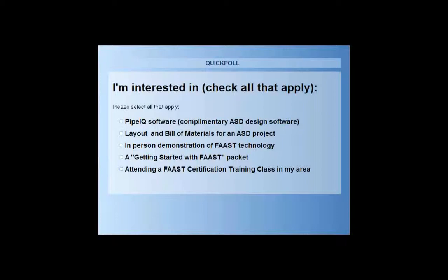A couple questions related to the Manitoba prison. Do we know how they made the points tamper-proof? Were they disguised or shielded in some place within that facility? I don't know the specifics on the Canadian project as far as the air sampling points. However, in some here in the States, I have designed with some engineering firms where we've hidden the capillary points inside light fixtures. In other areas of the cell, they very discreetly put them in there. Also, stainless steel sampling points are used in areas where tamper resistance is a concern.